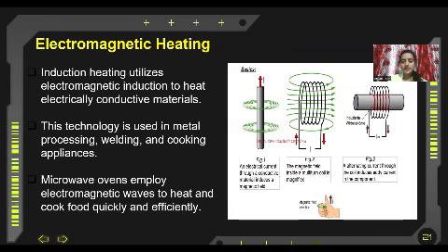As for the basics, in figure 1 we can observe that an electrical current through a conductive material induces a magnetic field. The magnetic field inside a multi-turn coil is magnified, and an alternating current through the coil induces eddy currents in the component.